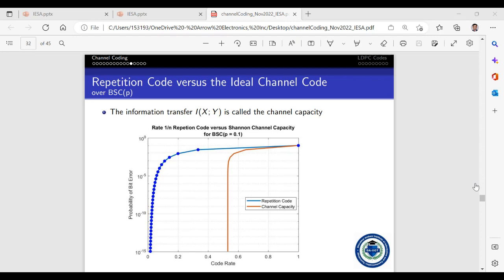But when K becomes small, suppose you have a sensor and that sensor collects only a tiny bit of information at a time, maybe 2 bytes or 4 bytes, maybe 16 bits or 64 bits or even 128 bits at a time. If you want to transmit a small number of bits, then the LDPC codes don't come very close to the orange line. And that is where the new advance that happened in 2007, polar codes, became part of 5G.